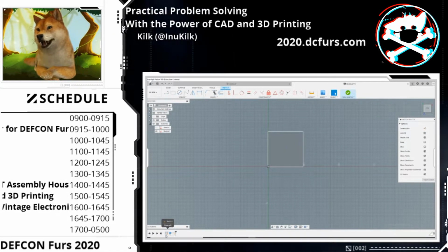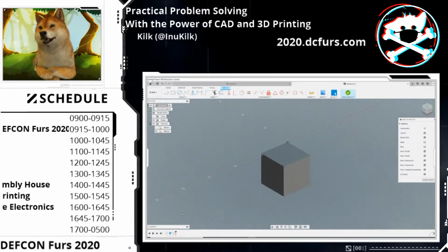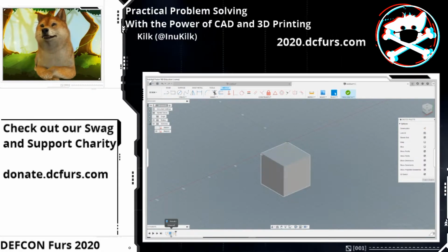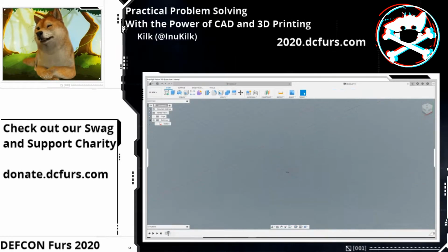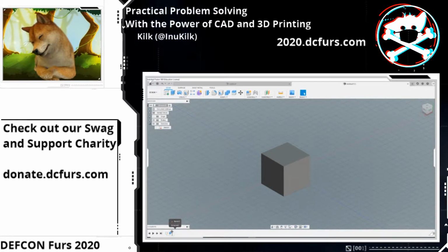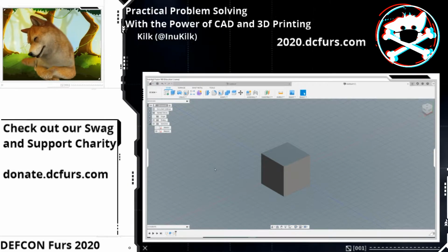So we've created a sketch. That was the first sketch. Now we've extruded it. Let me show you the sketch extrusion, and then we're creating a sketch on top of that face. So if we go back, right, now it's just a sketch. We go here. Now it's the cube because we've extruded. This is really useful because you can go back in your steps and see what you've done if you've forgotten, because you've come back to a project that you didn't work on for like 3 months.